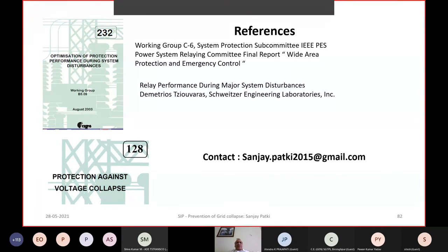Basically, if you are not familiar, you have to ask the suppliers to help you find why these inaccuracies are there. Mostly it may be that the voltage source is from the line CVT for one relay and from the bus PT for the other relay. That also could be a possibility.